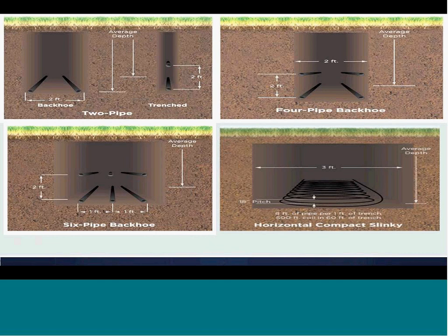Directional drilling is not the only method for installing horizontal closed-loop systems. The trend up until now was basically to provide a trench solution. This is much more practical and cost-effective in locations where there's a lot of land, for example, lawn, pasture, parking lots, and playing fields. Recently, the HDD, horizontal directional drilling, has been given more attention because of its ability to put the ground loop under buildings, ponds, or landscaping. And again, it also has the opportunity to reduce impact to the project site.